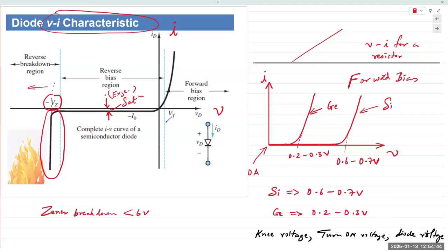You can input a voltage larger than the breakdown voltage, but the diode itself will hold its voltage constant. We'll talk more about that when we get to the section on Zener diodes. But this is the operating principle. Once a diode enters the breakdown region, it can carry large amounts of current, because the junction has broken down.